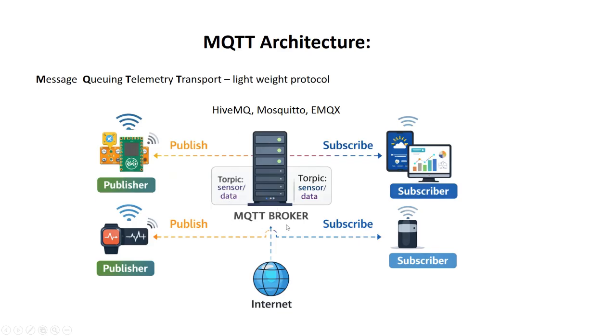Now, this is your MQTT broker. Your MQTT broker receives your messages and helps to forward them to any devices that subscribe to that particular topic. So your device could be maybe your web application or your mobile application or any other device that listens to information or commands from your Pico-W or from any other device. A subscriber must subscribe to the same topic that has been published by the publisher.